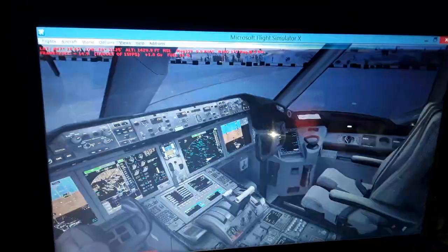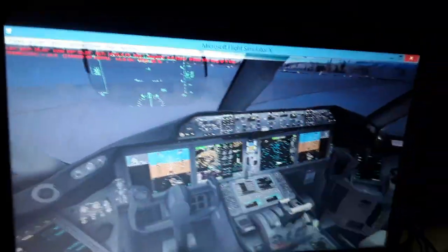So we have a different fuel mixture request every second. This is adjusted automatically every second as we fly, using the FADEC, the fuel mixture, also as we descend. So we don't have to regulate the fuel mixture all the time like we do in propeller aircraft. It's a good thing to have the FADEC installed in your engines.